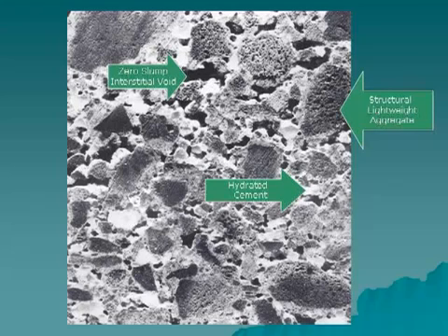Additionally, good shrinkage controlling practices include thorough mixing of the batch, sufficient wetness of the mix, and sufficient compaction. All these manufacturing techniques help generate products not only just passing strength tests, but also improved impermeability for longer masonry service life. Many of these concerns are now addressed with the advent of modern, dynamic block-making equipment now in use in the block manufacturing industry.